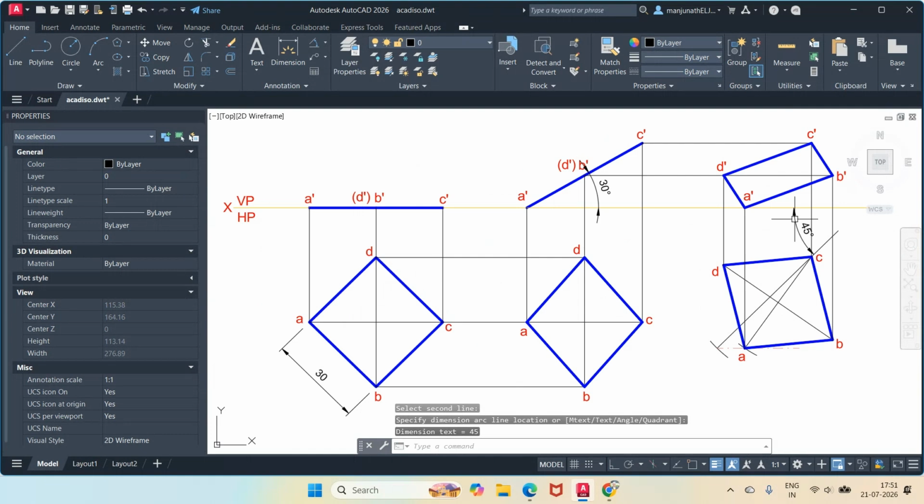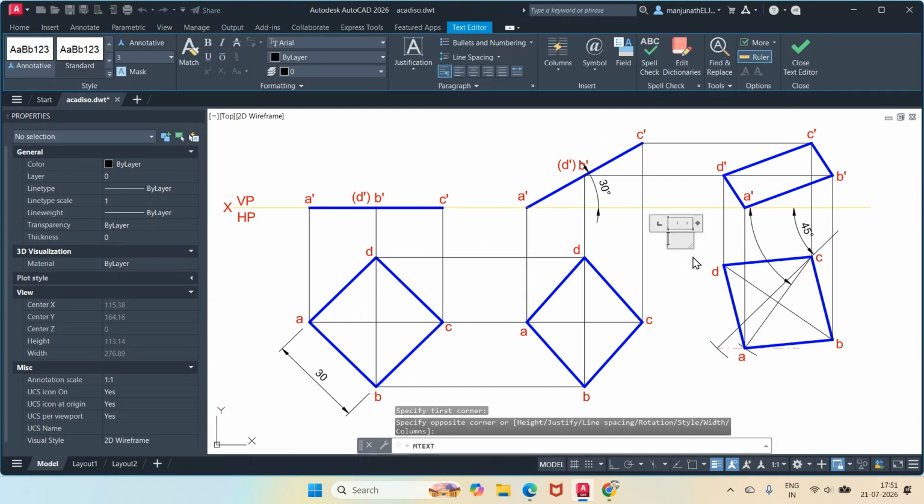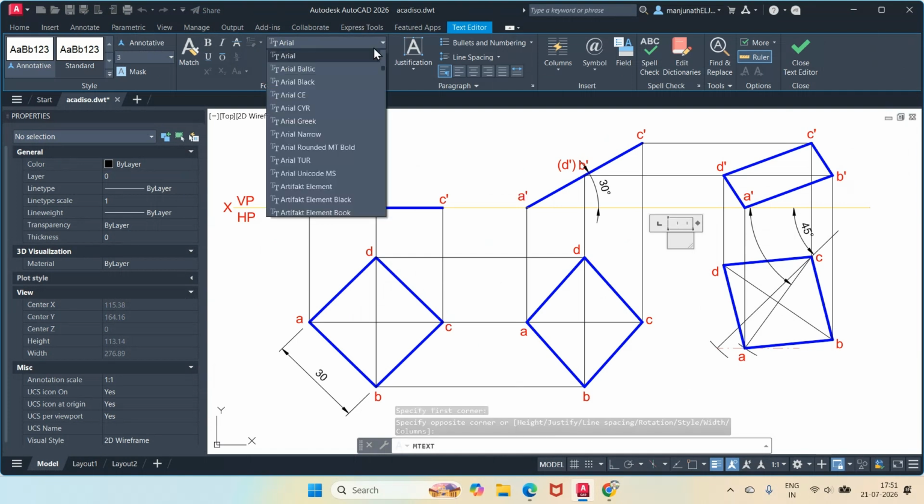Now you explode this. The moment when you explode, then it becomes individual. And go to text, select this and now you take this as, go to symbol, go to symbol, okay, type beta now, okay. Then you go to move, select this one and you move it here.